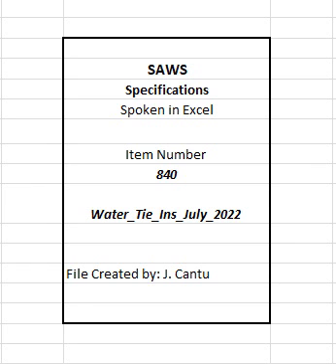5. A temporary water main, defined as a 4-inch main or greater, may be required to maintain customer services during the shutdown. SAWS approval will be required for the addition of a temporary water main. If approved by SAWS and there is no existing line item, a separate temporary water main bid item will be established and negotiated for payment.